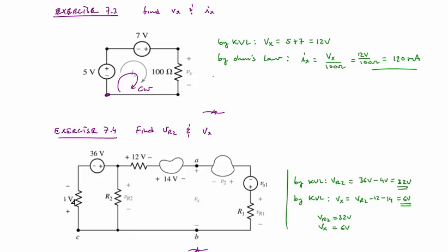Anything will do. So the other thing I choose is that whenever I encounter a minus sign, I will say I've just had a minus voltage. Even though if you think of it, the potential at this node here, at the positive end of the 5 volt source, is 5 volts more positive than it is at this end. So you could say, well, every time I encounter a negative sign, I'm actually going to add, in this case, 5 volts. And that's fine. But I'm choosing the convention that whenever I encounter a negative sign, I'll put minus. So here we go. We'll start at the bottom left corner, and we walk around clockwise.